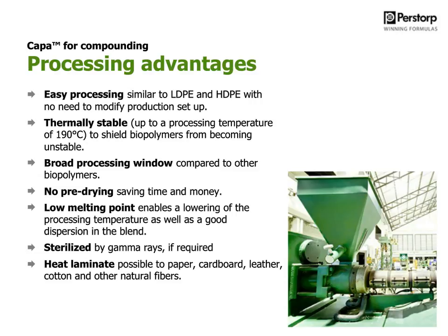So compared to many other biopolymers, it will be the least sensitive component. Working with starches or PLA, they are very sensitive, and if they have a very long residence time in the extruder, you will notice this either in the smell or the color. But here, the PCL will be the least sensitive one.